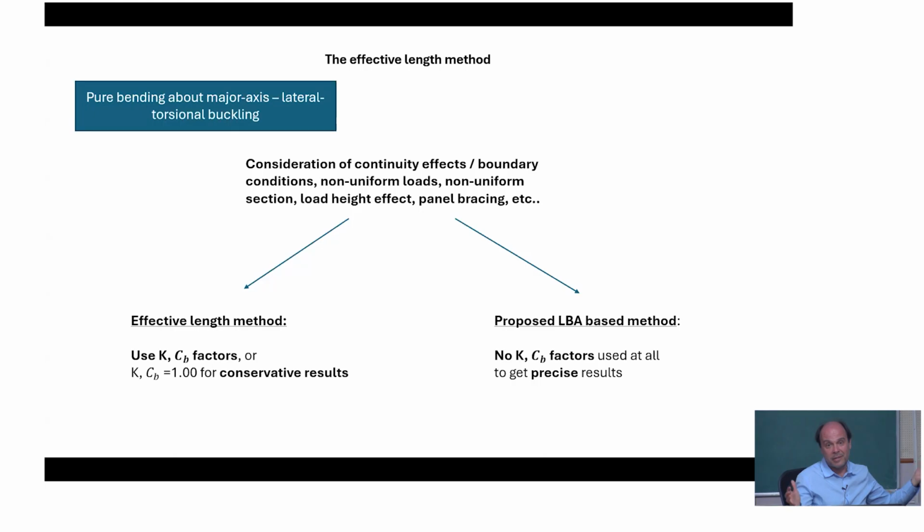The first is the past or the present, and it is the very general approach based on the use of closed formulas and these very traditional definitions like brace lengths and effective lengths. That's very, very well used in every standard of the world. It's used, but we can have something better if we use computers. By hand, this second approach doesn't work. To calculate critical stresses for these sorts of non-standard conditions is impossible. Okay?